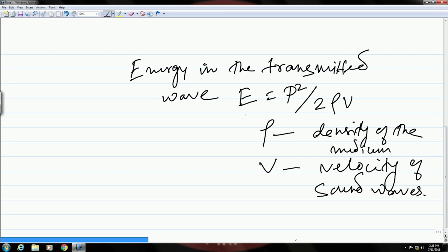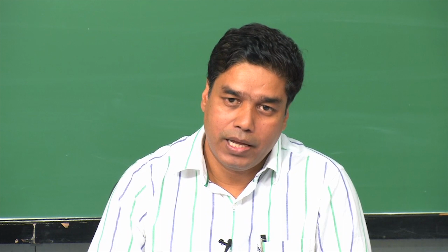So, you should have enough energy first of all in the transmitted sound waves which go to the sample, and then when it is reflected back, that reflected wave also should have enough energy, so that the instrument which is used for doing ultrasonic testing should be able to capture it.